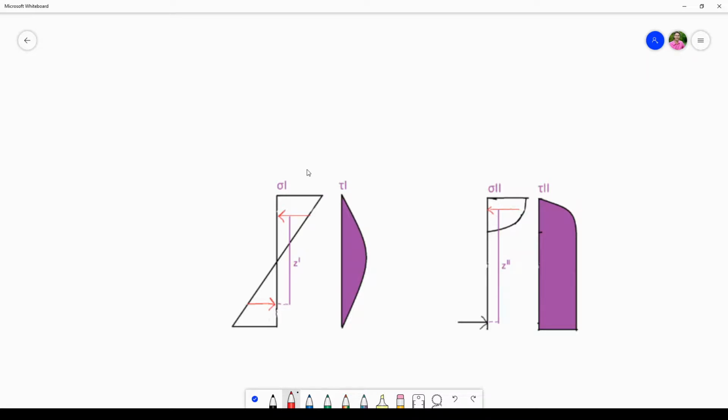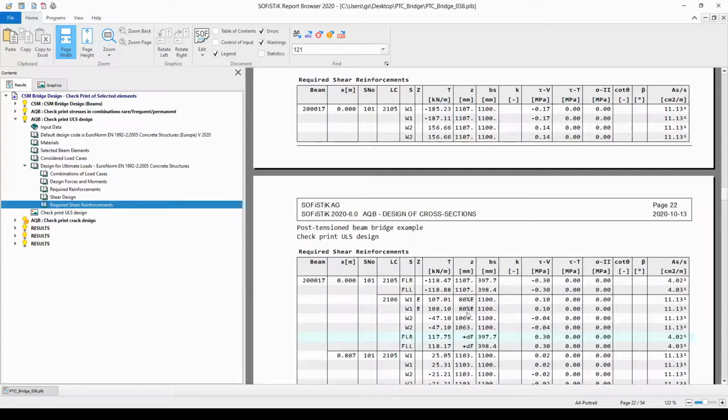However, a further reduction will be used, namely a stiffness reduction of the cross-section, and the amount of this reduction is the ratio between the lever arm in the first state and the lever arm of the second state. And this is what the 80% times E tries to refer to.